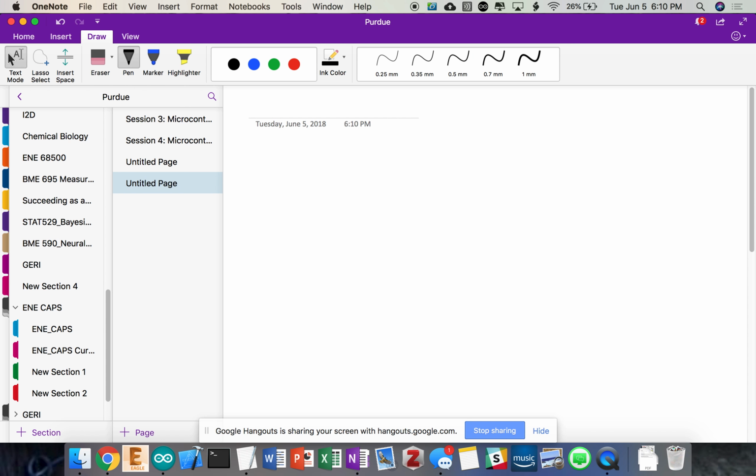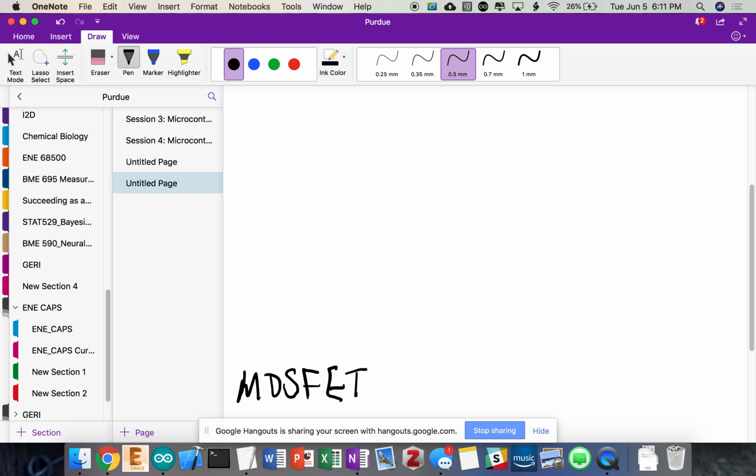So we're going to hook this up to our buzzer. I haven't given you guys the buzzers yet, but essentially they have two leads. One of them can be longer or shorter than the other, but somewhere on the buzzer it's going to have a plus on one side. That's the anode, the positive side. I'm going to use the symbol for a piezo element here.